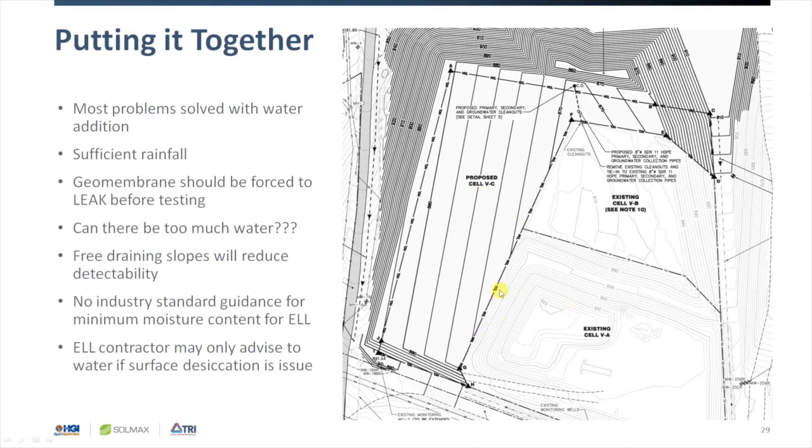So when we have a configuration like this and we can't control the water inside of the testing area, we'll suggest that it be watered, say, the afternoon before the test, and then let it sit overnight for that excess water to drain out. Then we can test it first thing in the morning, when it's still pretty nice and moist, but we don't have a lot of water actively flowing off.